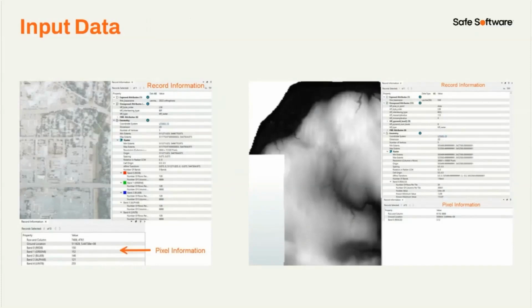We begin with our 3 primary datasets. The road center lines in GeoJSON format, providing the vector framework for feature alignment, a digital elevation model, a single band raster where each pixel represents a height value, and an orthophoto, a multi-band raster containing red, green, blue, and alpha channels for true color representation. Understanding these inputs highlights a key imagery concept, that raster data can store either numeric or visual information. The DEM represents elevation values, while the orthophoto represents reflected light. When both are aligned spatially, they can form a complete ground model.